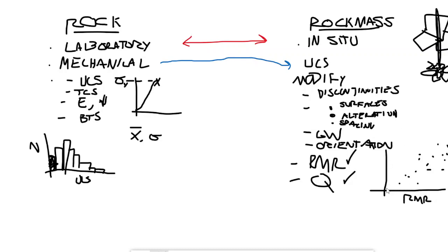And so what you'll see is, again, this conservative estimate where, if you look at all these different factors and probability of failure, we'll label that, right? If this is the probability that an excavation fails, or a wedge comes down or something like that, you'll generally see a fit that tries to encapsulate all of the data above it, or probably below it. You want to underestimate the strength of the rock, the ability of it to support itself, and deal with that